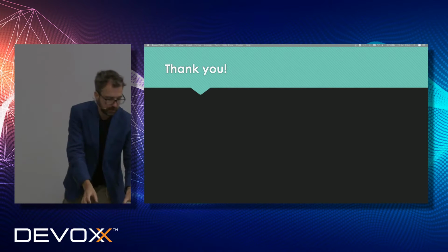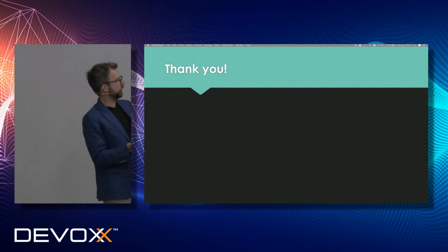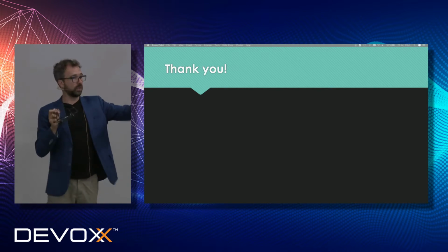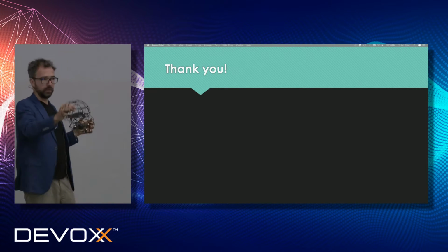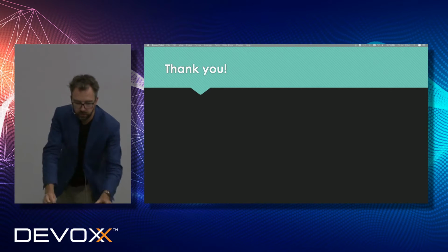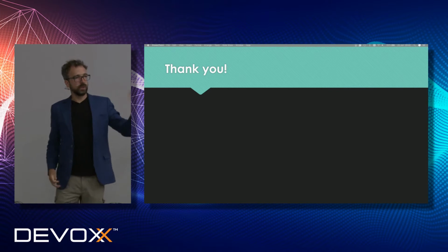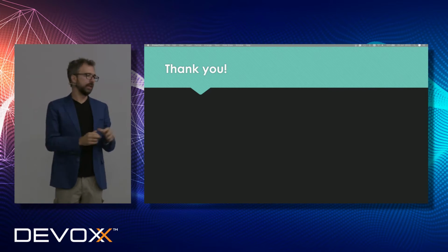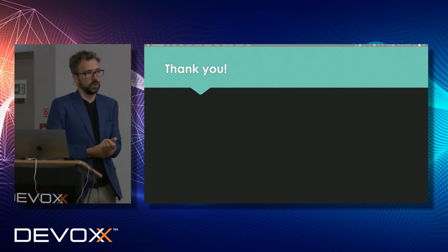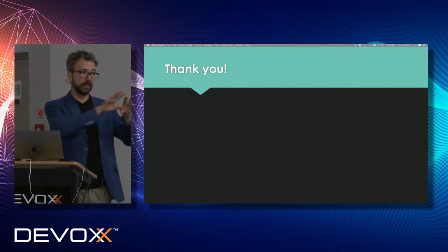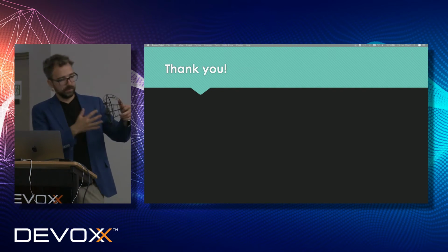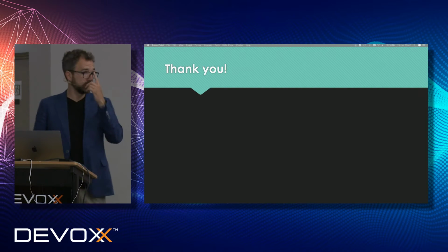The big problem arises if you have several drones at once, because if you have a camera over there and you have two drones flying like this, first of all, it's hard to figure out which drone is which. So you see two drones, but how do you know this is the white and the blue one? Of course, it's white and blue, but I'm not sure if the camera will see. So if you start flying with a lot of drones, you need something on board. Visual recognition is one of the options. I've also seen initiatives with Bluetooth, where they take the signal strength. But as soon as you're doing it on board, then you're limited by the hardware.